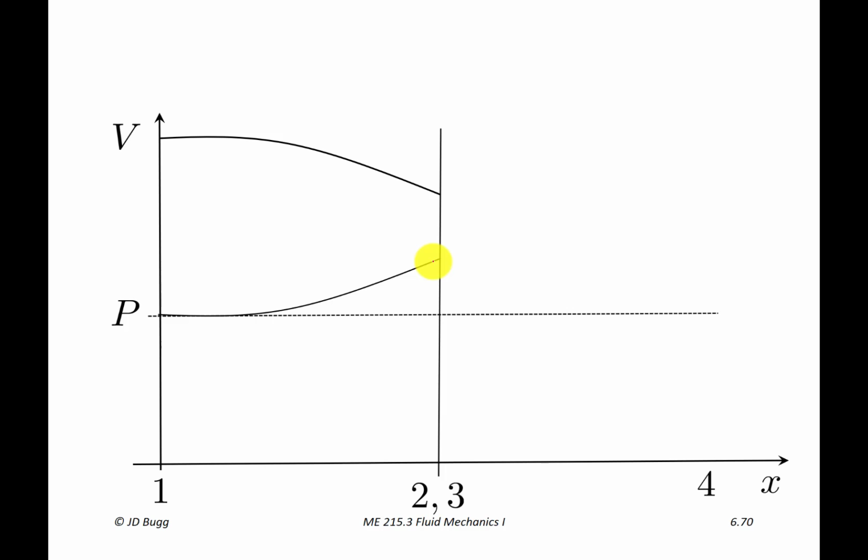Now, as the air passes through the rotor plane, however, there is a pressure drop. So this thick line that is shown up here is meant to show that. So we've passed through the rotor plane, the pressure drops down. So there's an obstruction there, air flowing through it, decrease in pressure. But remember, the velocity doesn't change.